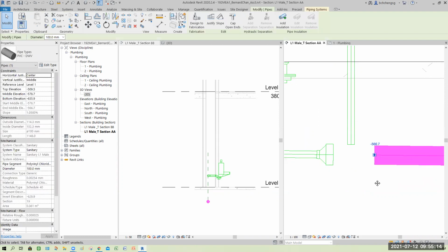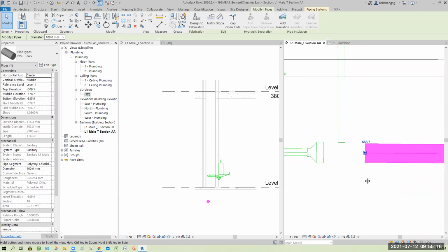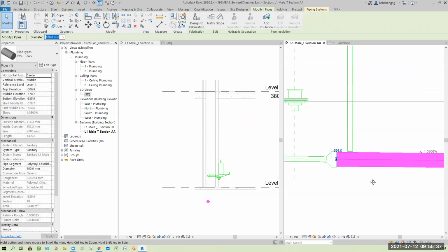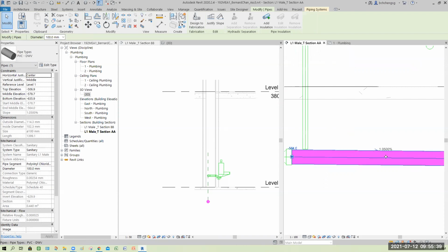So here, hopefully you guys can understand how this thing is connected. While you are dragging it, remember, not horizontal. Fidget a bit, you should get something like this. It says parallel and nearest. So from there, you get to maintain. The important thing is what? Your slope percent. Okay, so slope percent achieved.